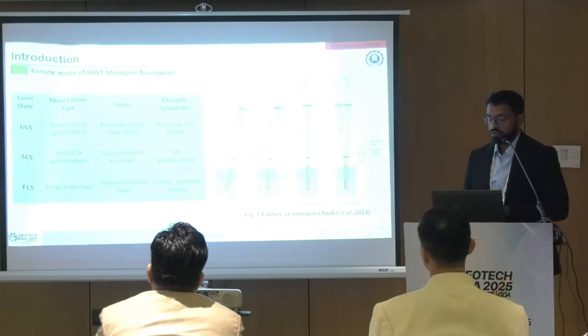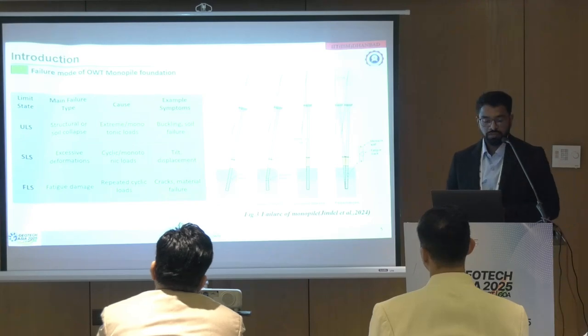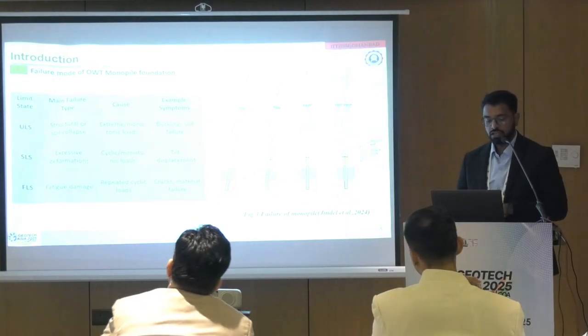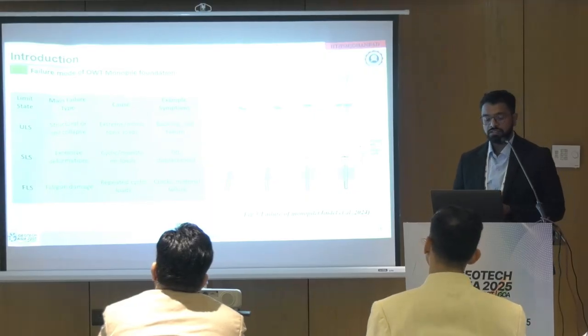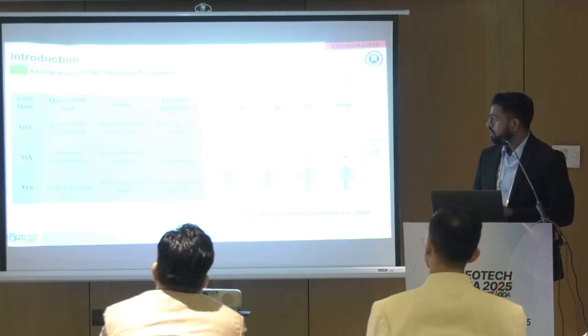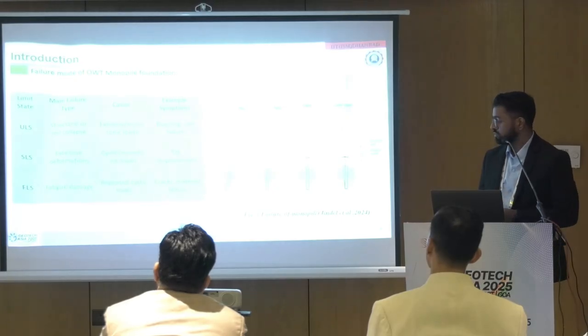The failure modes of offshore wind turbine foundations are: the ultimate limit state, which is structural or soil collapse, with symptoms such as buckling or soil failure; the serviceability limit state, with excessive deformation, where tilt and displacement are the symptoms; and the fatigue limit state, where cracks or material failure occur.